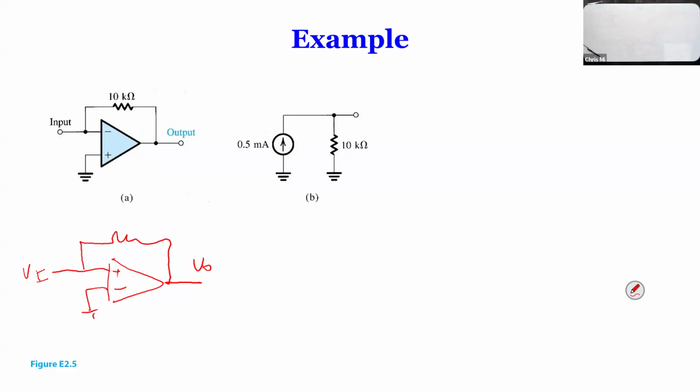Let's say if input increases, output increases, that's like a typical open loop amplifier. The more input, the more output. Now, if there's a positive feedback, what happens is if input increases, output increases, and the difference at the input increases, the output is even more. The input increases and the output increases even more. So it goes back, the output eventually goes to saturate. So that's a positive feedback. But negative feedback is exactly different.